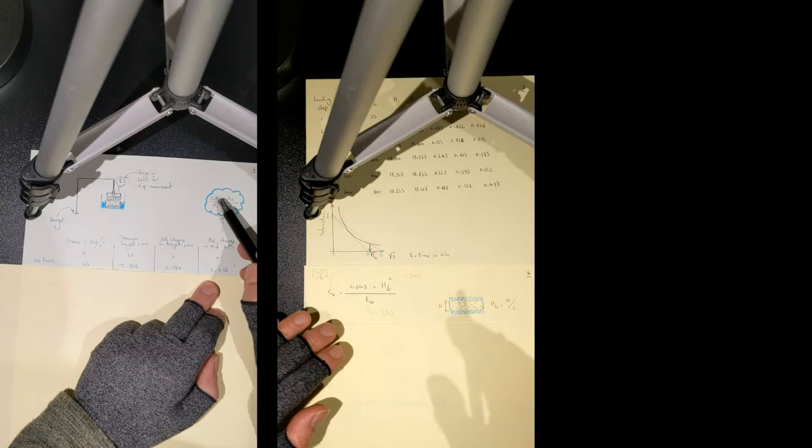Delta H, the subsidence, divided by H0, the initial height of the test specimen, in your case 20 millimeters, equals delta e, the unknown, divided by 1 plus e0. Well, you remember that we know how to measure e0 from all the equations that I presented earlier. Let's look into these equations.